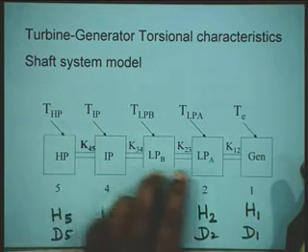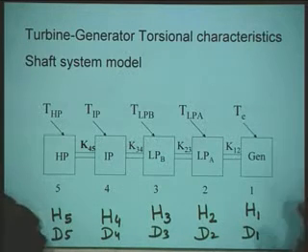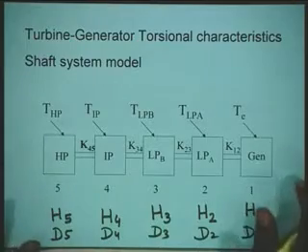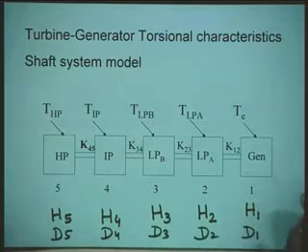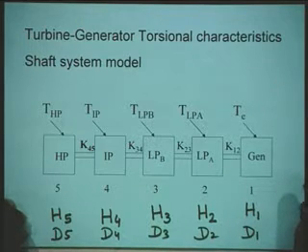Damping is also produced by the mechanical hysteresis of the shafts connecting the various turbine sections. Therefore, there exists some damping in the system. However, the damping produced due to these various phenomena is very small in magnitude. We will develop the dynamic model of the system assuming a certain finite value of the dampings associated with the generator and steam turbine sections.